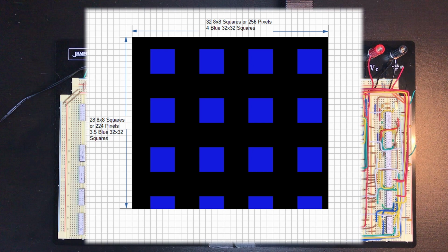The size of the square is just how the input signal, in this case 32, compares to the pixel clock. Our pixel clock is equivalent to the H1 signal, so that makes sense that the H32 creates a 32 pixel box.